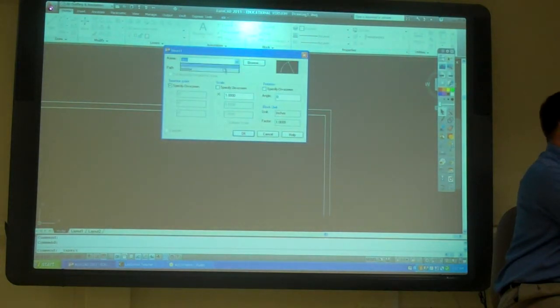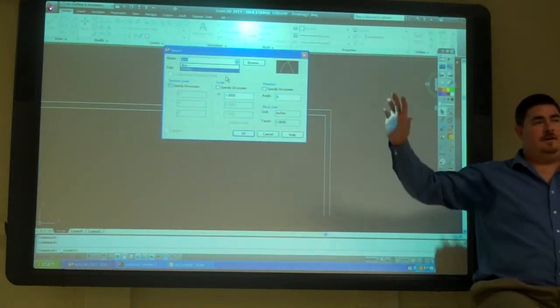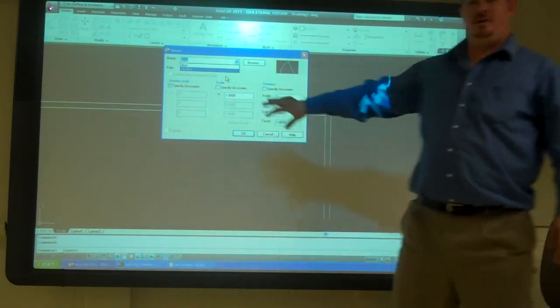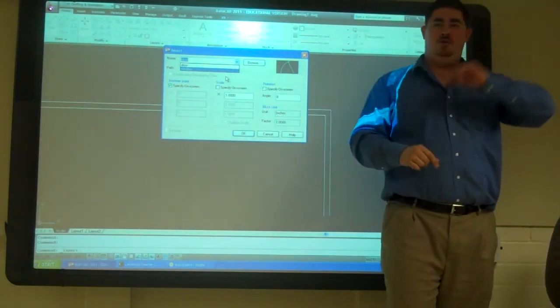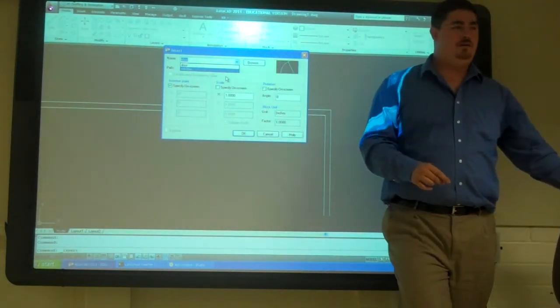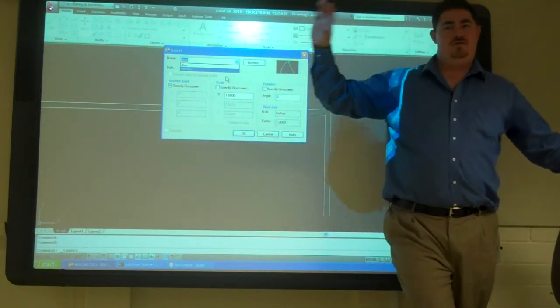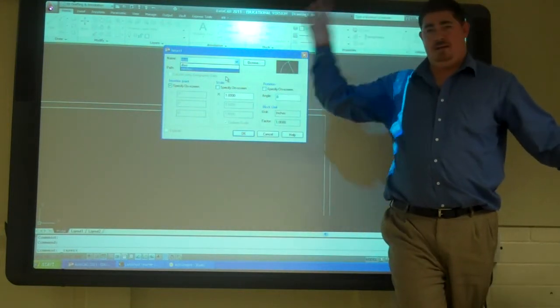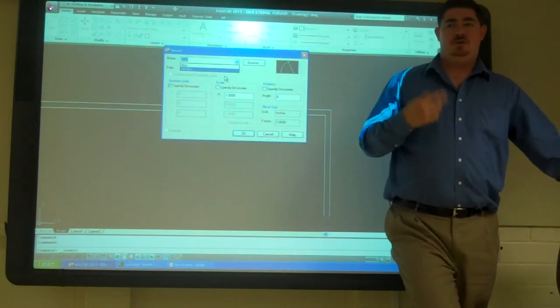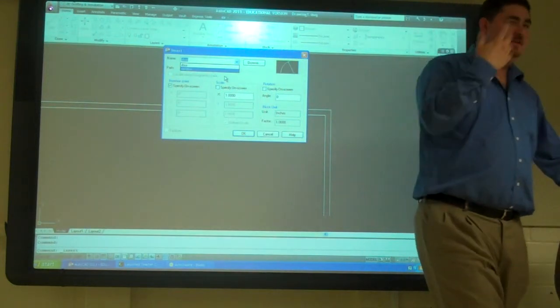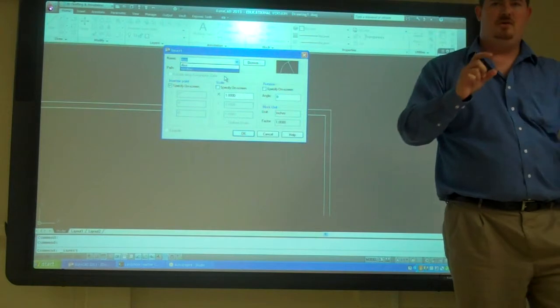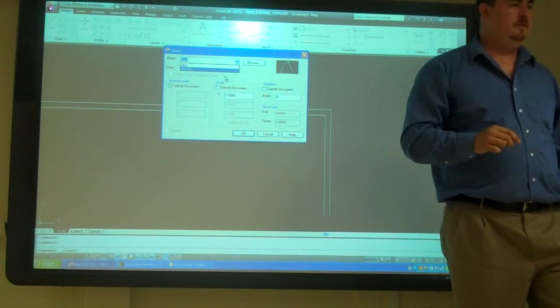And here those are. And they're part of this drawing file now. So anytime I open this drawing, they're going to be there. If I open a new drawing, they're not going to be on that new drawing. So it's for that one drawing. If I copy and paste them to another one, I could do it. We can also do what's called a W block. So if I insert this, I can make a W block out of it, and it actually just makes a whole new drawing out of it that you can insert.